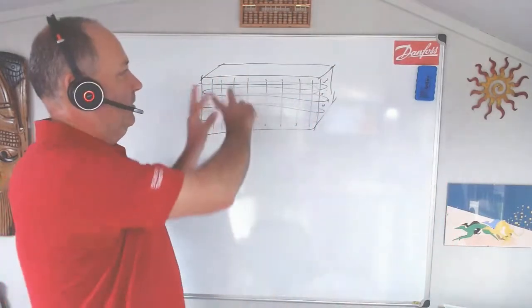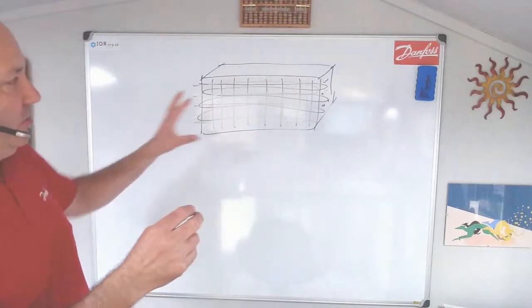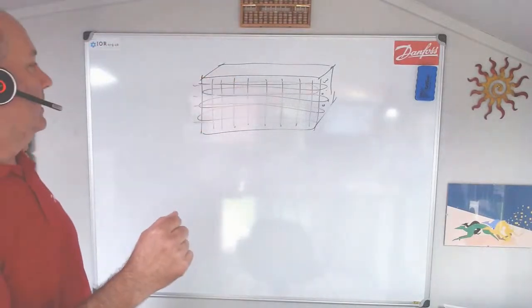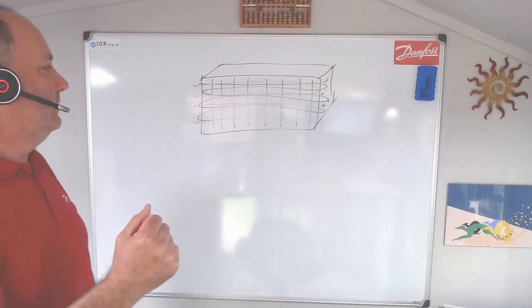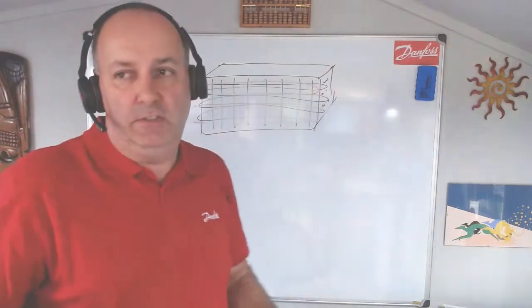Somebody said, is there a quick fix method if the defrost heaters are not working? Unfortunately not. You need to take that heater out. What I've scribbled on the whiteboard there, I suppose it's a quick fix to add extra heat to the coil, but it's not perfect. You're much better replacing the faulty defrost heaters.